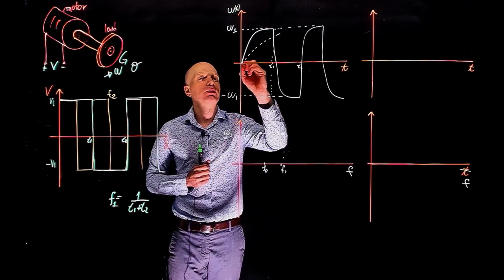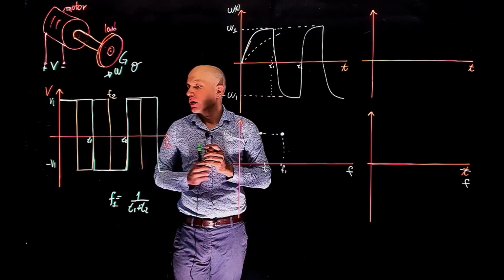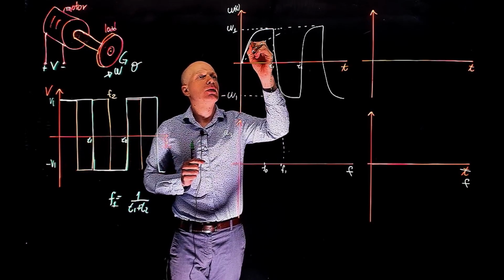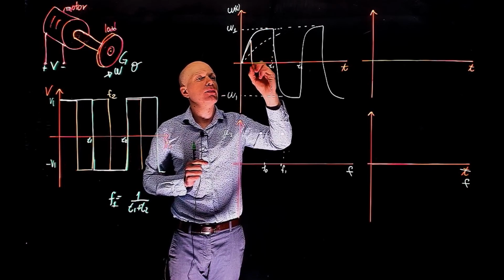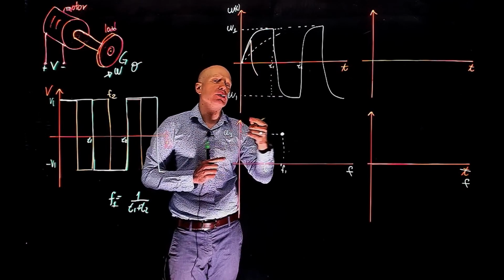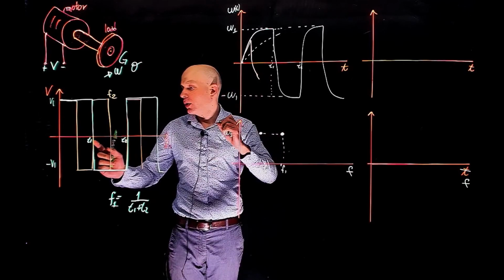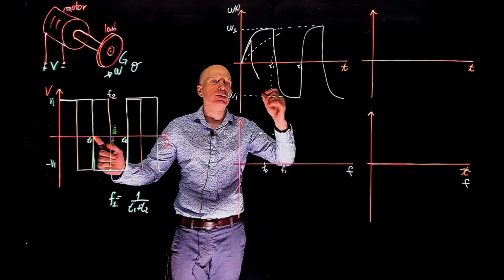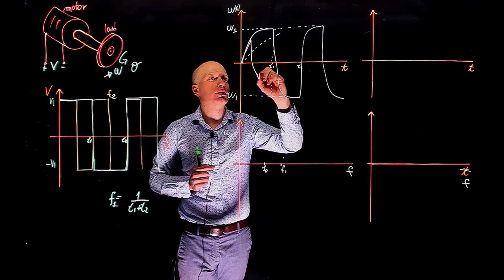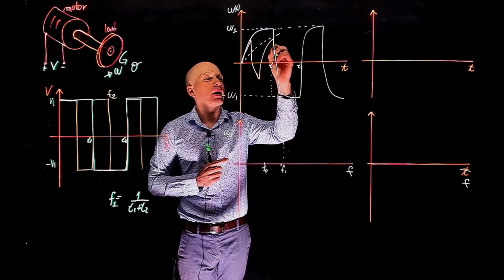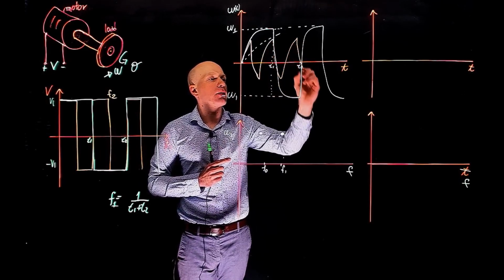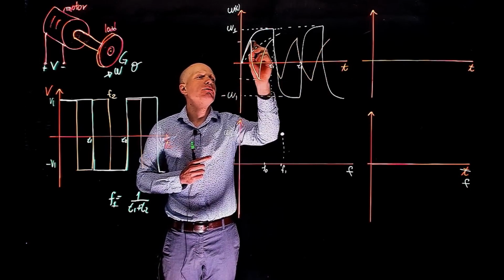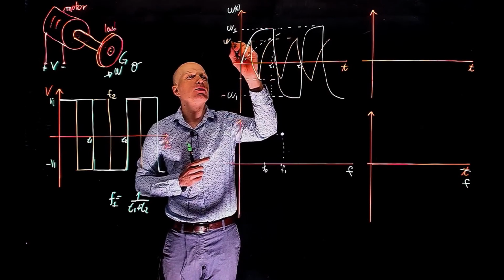So when you turn the motor on, it will start to go up. And when you reach now your new time here where we reverse the voltage, we will stop there and the motor will now go down in the speed and go in the opposite direction. We now reach this point, where again we switch the voltage and now the speed reverses. So now the speed goes back up and back down and back up and so on. We notice here that we reached a different value for the final speed. Let's call this value omega 2.